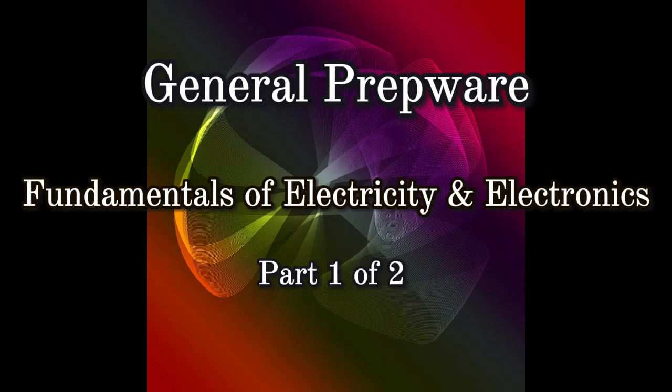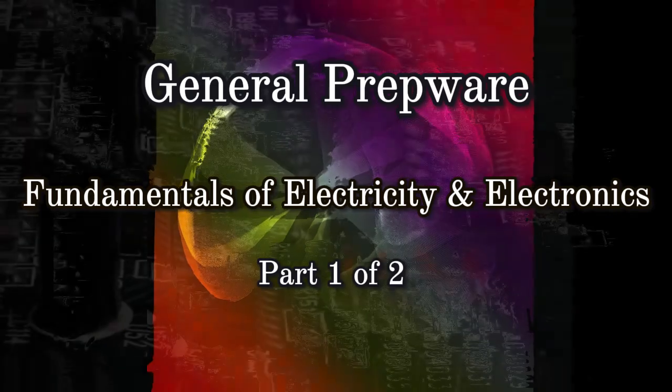Which of the following statements is or are generally true regarding the charging of several aircraft batteries together? Answer 1 and 2. 1. Batteries of different voltages but similar capacities can be connected in series with each other across the charger and charged using the constant current method. And number 2. Batteries of different ampere-hour capacity and same voltage can be connected in parallel with each other across the charger and charged using the constant voltage method.